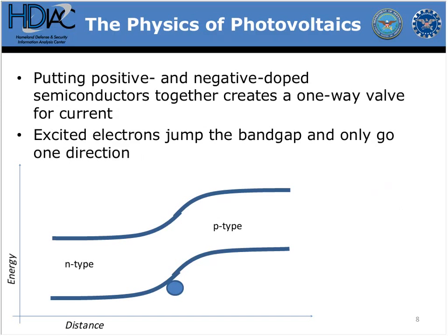By itself, the semiconductor, even with its bands, is not useful for PV until we dope it. The concept of doping is to give a semiconductor a higher or lower electron population. It doesn't change the size of the band gap, but when you put a negative doped semiconductor, denoted as N-type, into contact with a positive doped one, P-type, it can make the higher or lower energy bands relative to each other.